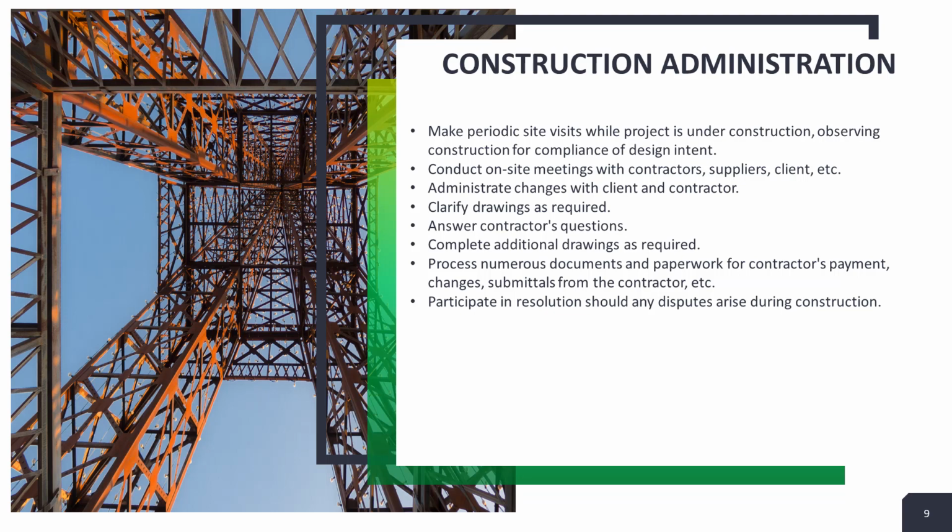During this process, we also have to review documents and lots of paperwork. This is where we do the changes. We have to look at the payment that goes to the contractor, submittals from the contractor, or what we call shop drawings, and then any kind of resolution that needs to take place between disputes. We also deal with that. Say, for example, if the concrete guy said he would be there next week and he doesn't show up for 2 weeks, the owner's not happy, we are the middle person to do that. The architect is the owner's representative.